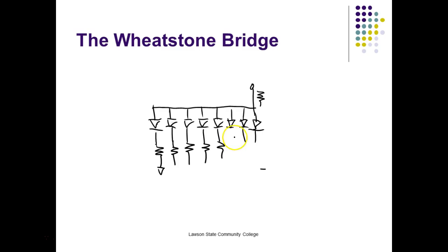Now, PLCs have no problem with this. In digital, we have special integrated circuits that actually generate an output for us. 7-segment drivers. We have a 7447, which is a common anode driver, and then we have a 7448, which is a common cathode driver. They take a binary code, we call it BCD, and they turn on the segments. So if you put the code for a 7 in there, it would turn on the right segments to display a 7 for you. It would automatically do that for you. These guys have been around for a really, really long time. 7-segment display.